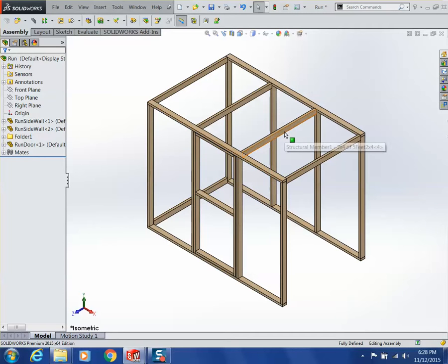Alright, now into the bulk of what I was hoping to get to. A lot of the tips and tricks and everything else that I'm going to talk about is going to drive back to this idea of design intent, which SolidWorks has thrown around since the very beginning because that's the whole mantra of how they want to drive a lot of things. And design intent is basically designing your part so that it works the way you want it to. To put it another way, if you follow good design intent, if you are able to capture it nicely, when you walk up to the part, you should be able to make changes really fast and have the things that you think should update will update.